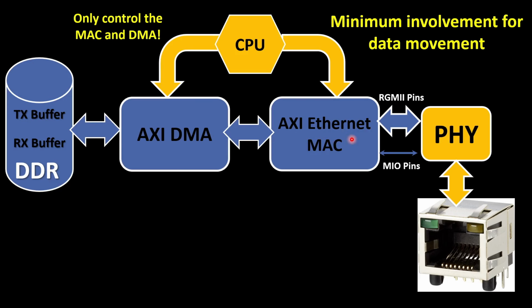And with the help of them, the AXI Ethernet IP can set up and configure the PHY chipset, and it can also see and monitor the status of our PHY. And then the PHY will directly connect to the RJ45 connector. So for sure here, because we are going to work with the 7 series again, we need to have the MIG, memory interface generator, and then we can have access to the PL DDR memory.